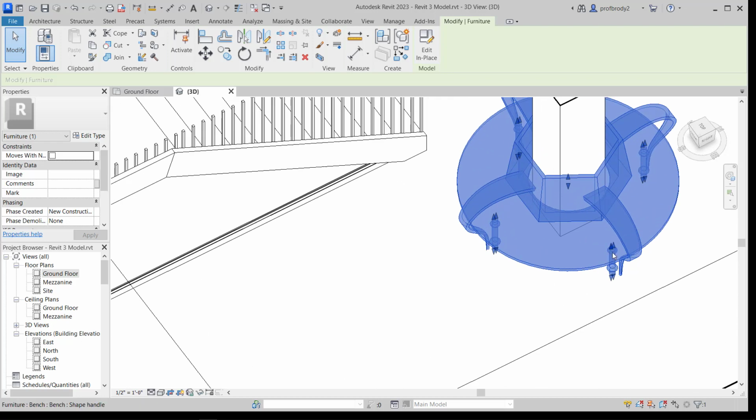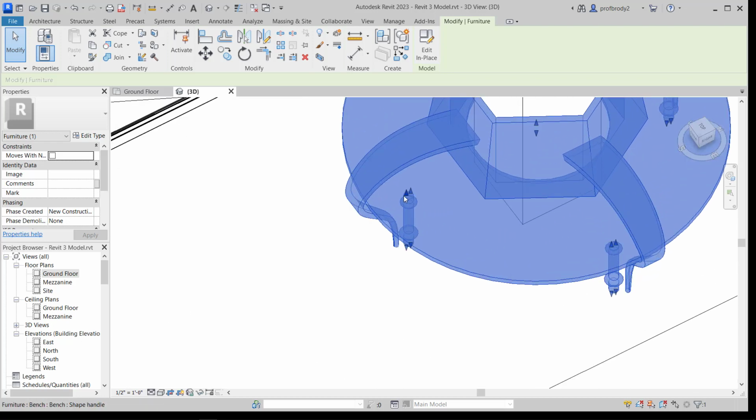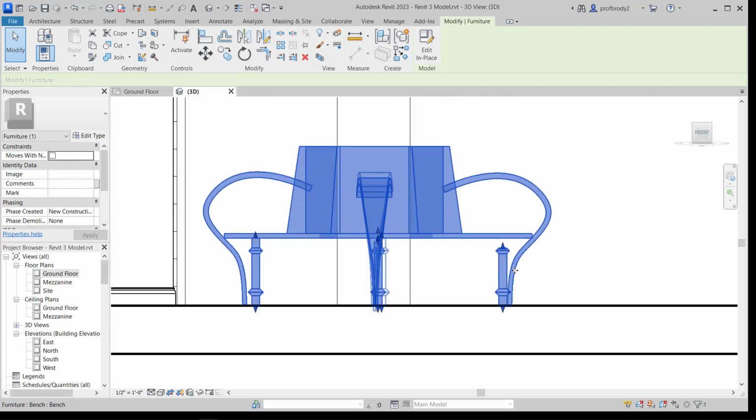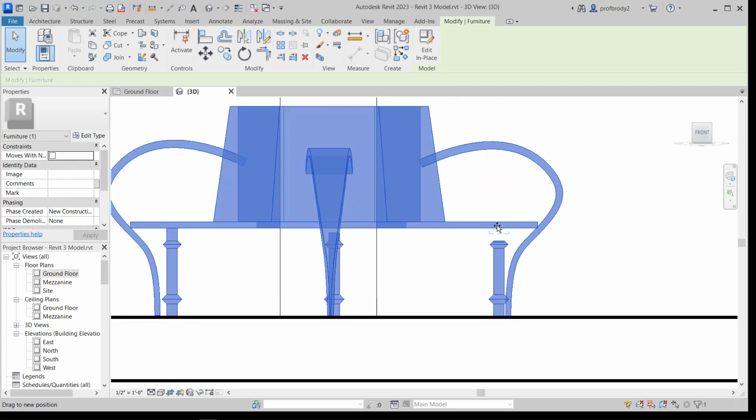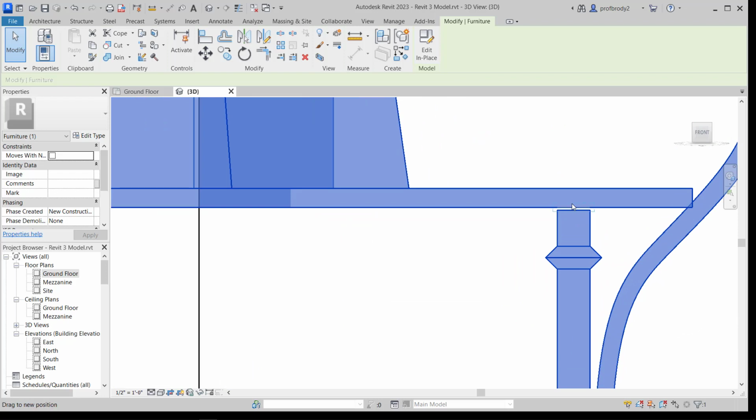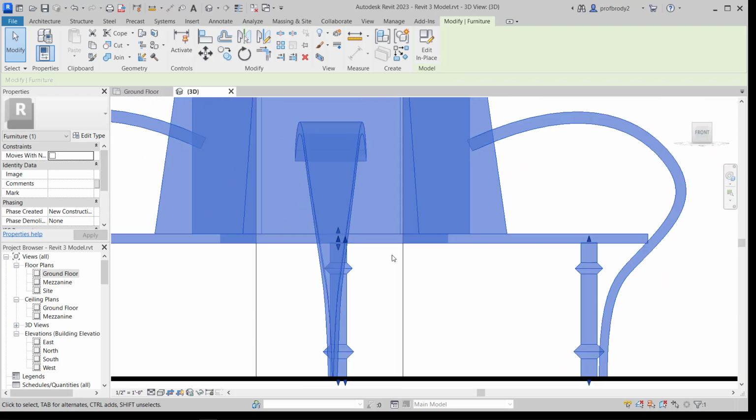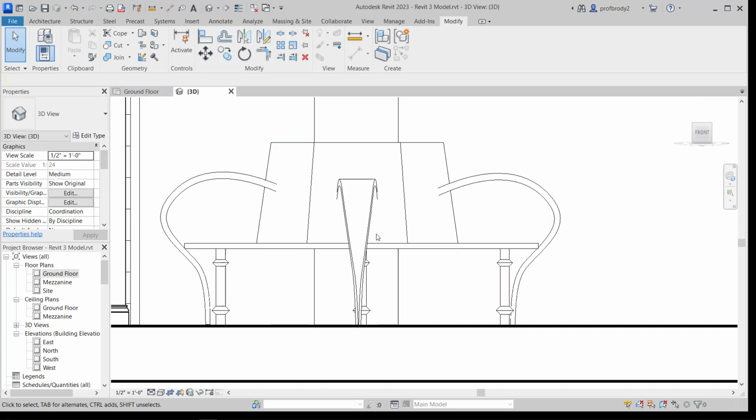You will also notice that there are these grips visible on all of these, and these allow you to modify objects after the fact. For instance, this one I must have dragged down. I can drag it back up again. The trick is always seeing what it is that you're modifying. And if things are not looking right, and I'm never going to see this underneath here, but if I were, you could use the Align tool to get yourself a nice looking object.